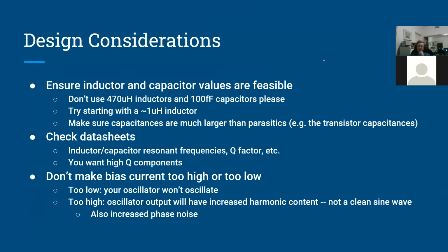When you're building power systems, or working with DC voltages, or a 555 timer, for example, you use capacitors in the microfarad range usually. And for decoupling microcontrollers, you might use a 10 nanofarad or 100 nanofarad capacitor. For RF systems, when you're working up in the megahertz or gigahertz range, capacitors are usually in the tens to hundreds to thousands of picofarads.